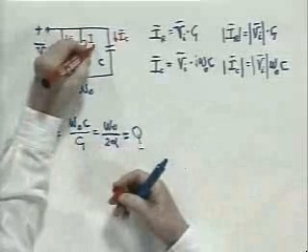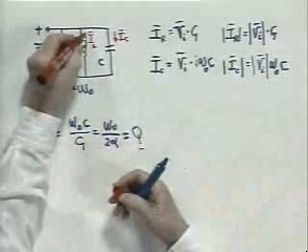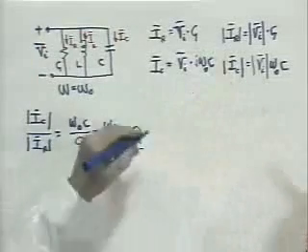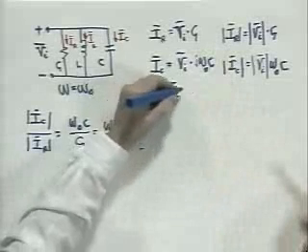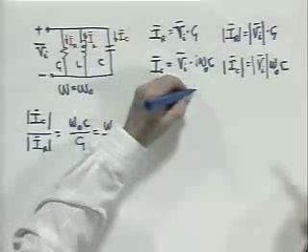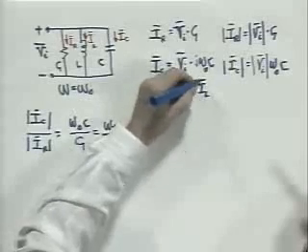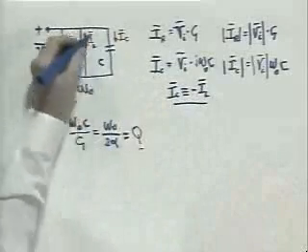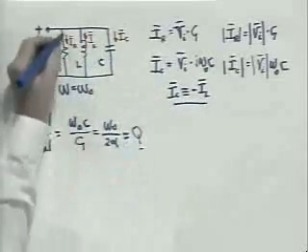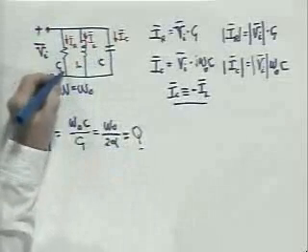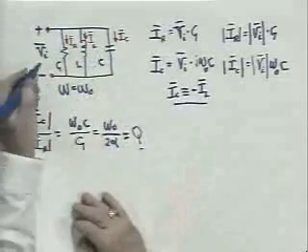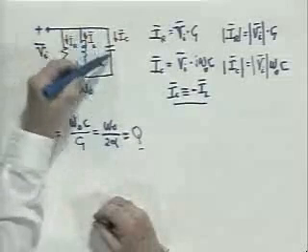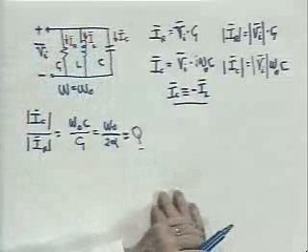That is, if this is I sub L, complex amplitude, flowing in the inductor, if you follow through the complex arithmetic, you will find that I sub C, complex number, is exactly equal to minus I sub L, complex number. That is, these currents cancel, and there is a circulating current that flows in this LC pair, which is Q times as big as the current flowing in the resistor. So while the circuit at resonance looks like a pure resistance, you shouldn't ignore the fact that there's a whopping big circulating current flowing in the parallel LC combination.